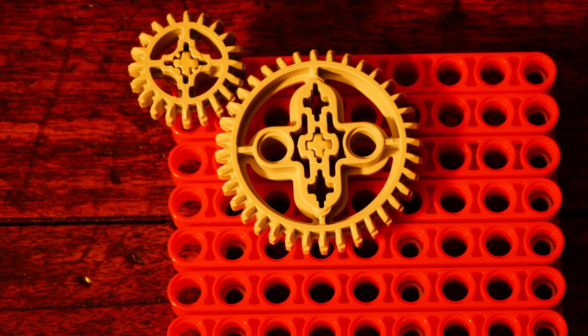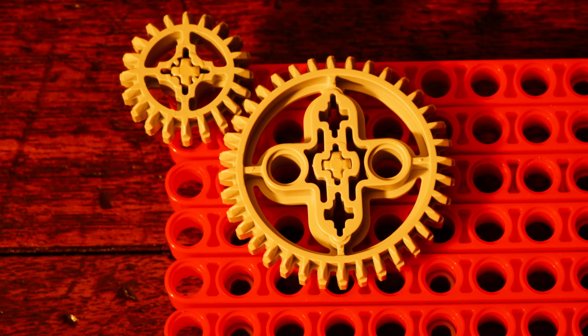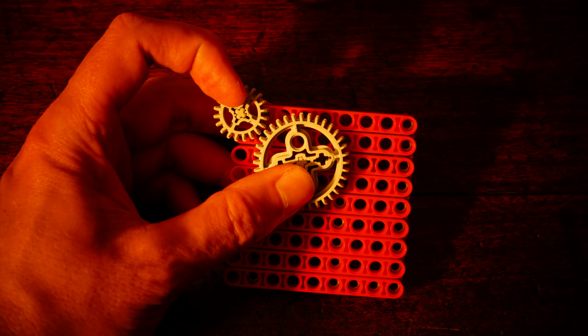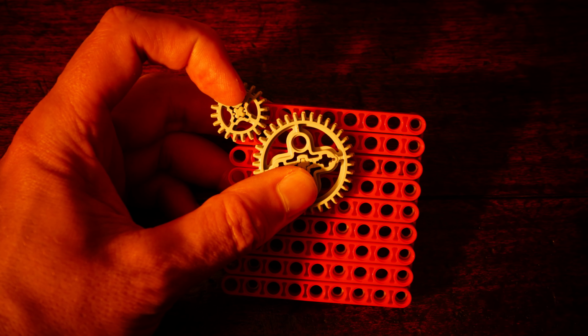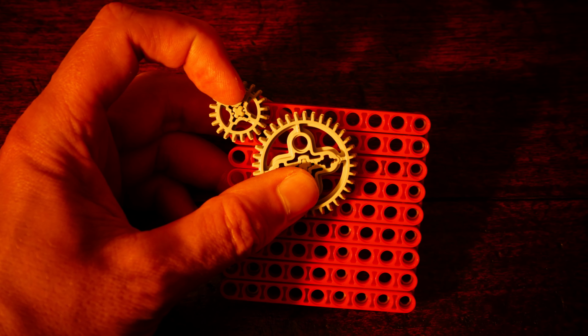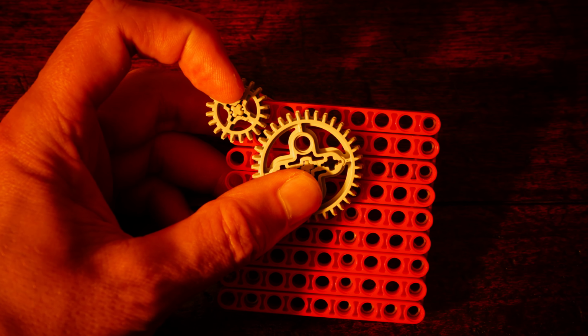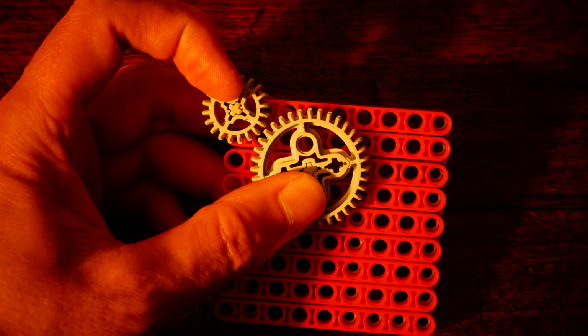But wait, the gears sort of mesh, but there seems to be a substantial gap between the teeth, more than usual at least. And upon closer inspection, it is apparent that the gears can be pried apart rather easily. So this gear train might not be a good candidate for high torque applications, because the gears might slip. Thus, non-orthogonal gear trains can be especially useful.